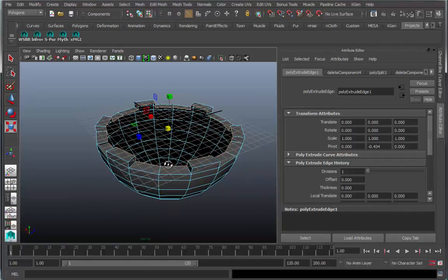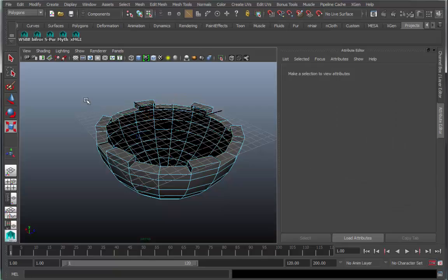If you have extruded once and then you forgot and then you extrude again, be very careful. You've actually created double geometry. That can get very tricky. So be very careful about this process. You can't continually grab the same edge and then extrude, forget to do something with it, and then try to grab the same edge and extrude. What you'll have then is dozens of points of geometry all sharing exactly the same space, and that can really mess Maya up. So I made sure that I had only one ringlet selected.